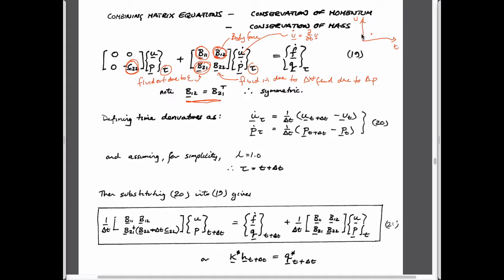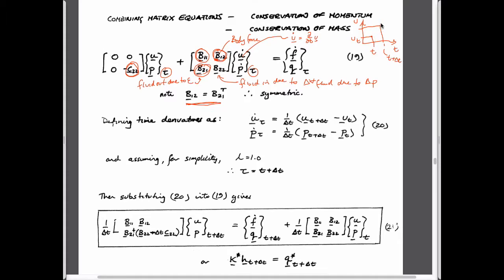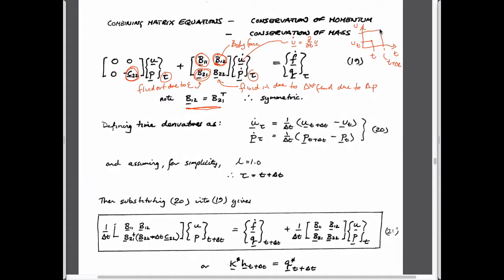We have some displacement at some time, and another displacement at a different time, t plus delta t. We link those through by some curve. This is u at t plus delta t. And the slope of this curve is exactly this, just by doing the differencing.